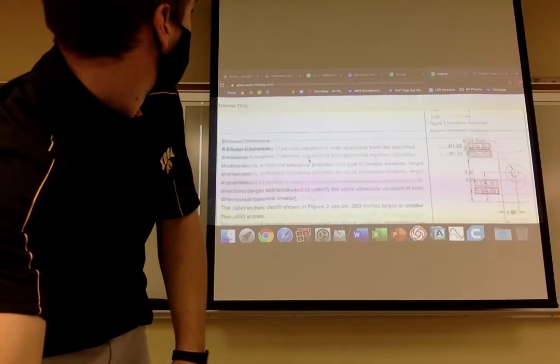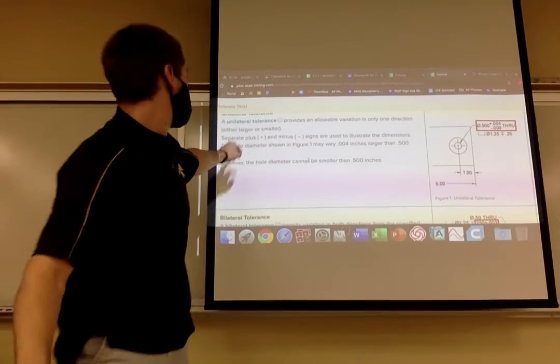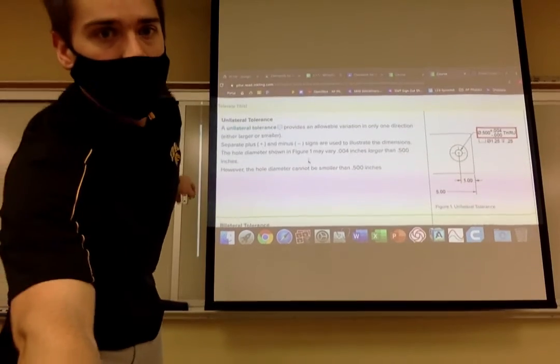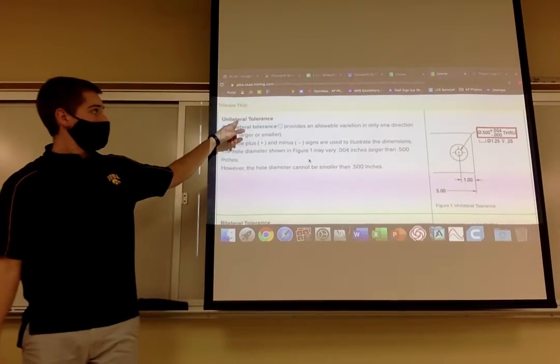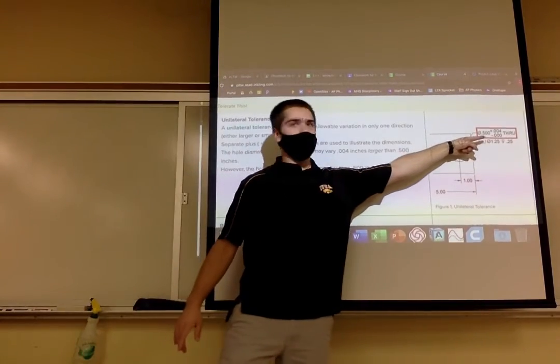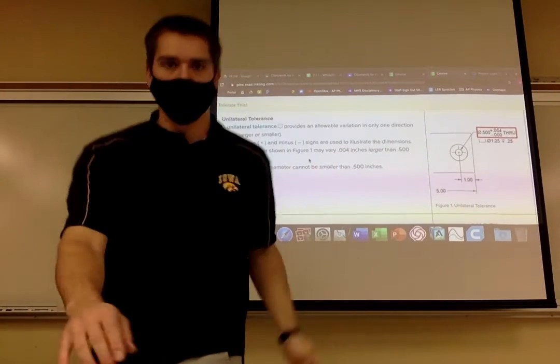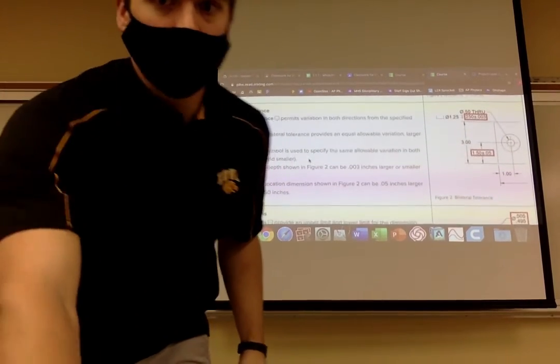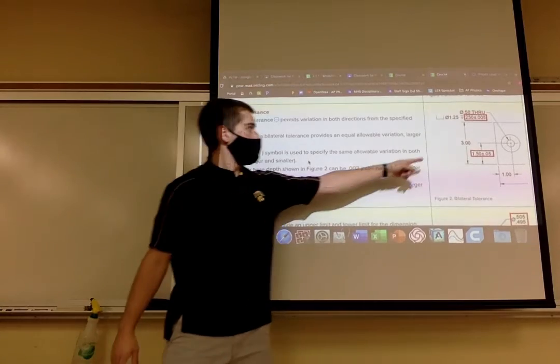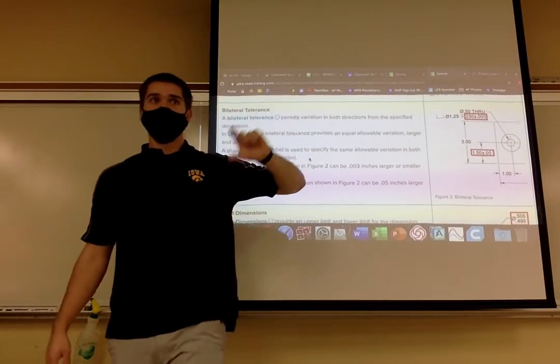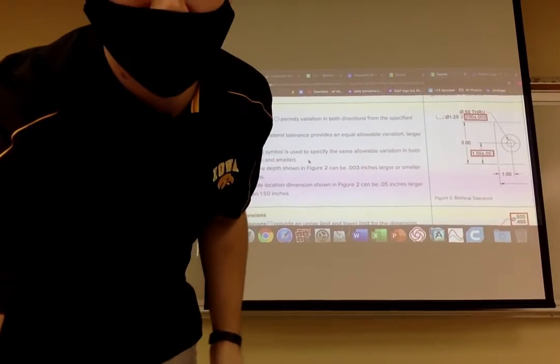Again, unilateral tolerance for that first one: I only give room for error in one direction. Bilateral, I give it in both, plus or minus. You have room for error in either direction.